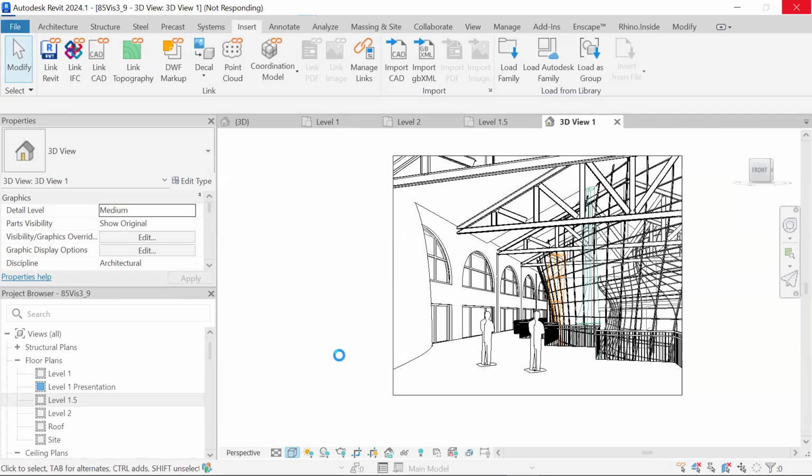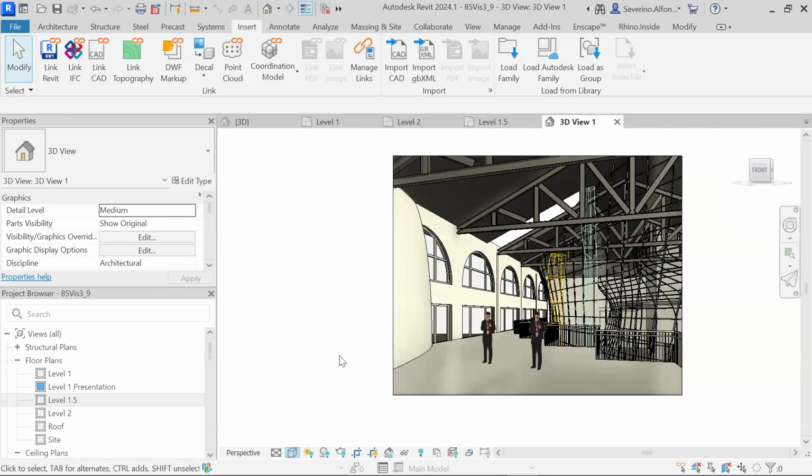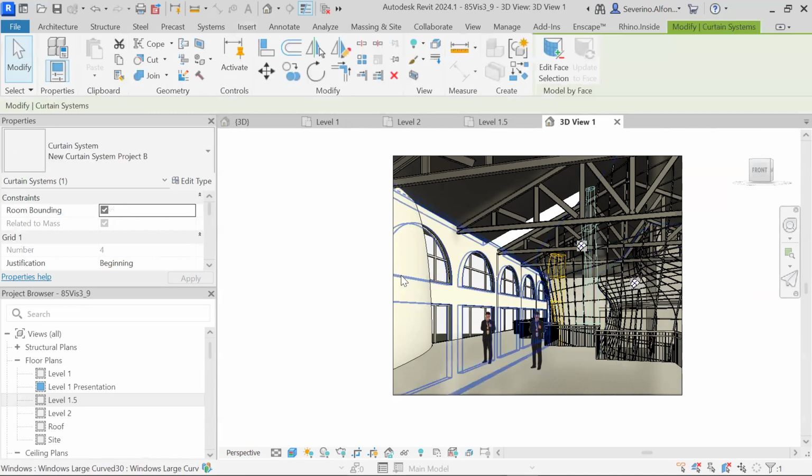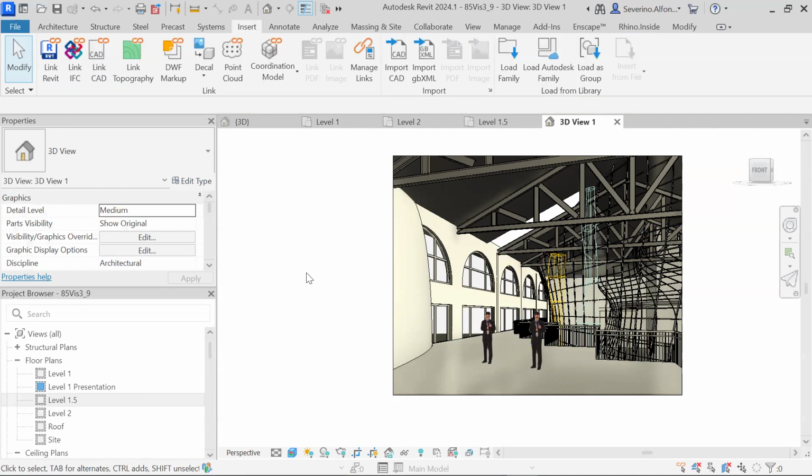Now, notice that I'm not using the SAT option. I'm using actually the DWG option. The SAT is a great option for selecting surfaces afterwards and applying surfaces or walls to surfaces and so on. Okay.